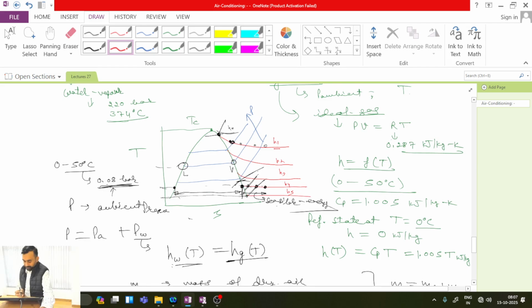On the contrary, at low pressure, the enthalpy lines in the gaseous phase become almost horizontal, which reflects that the dependence of enthalpy on pressure diminishes, and enthalpy becomes a sole function of temperature only.